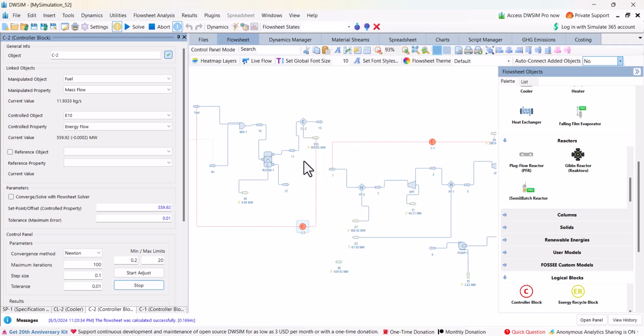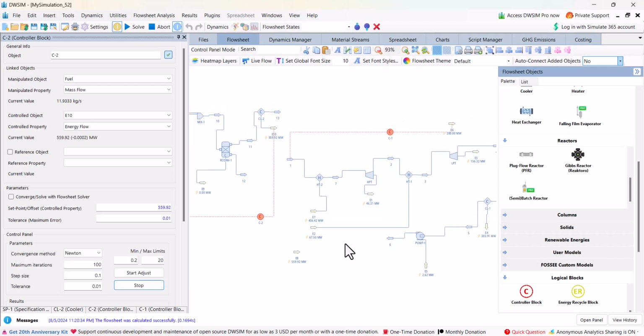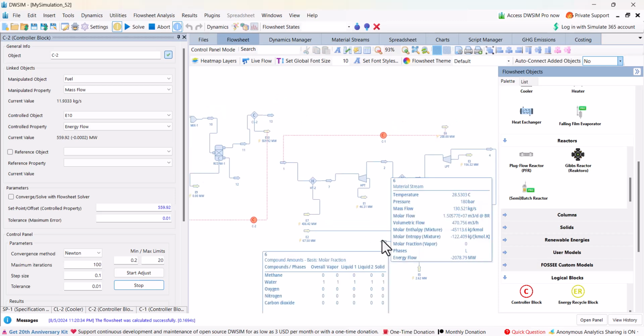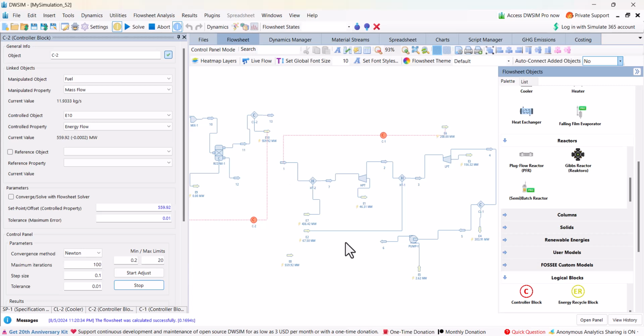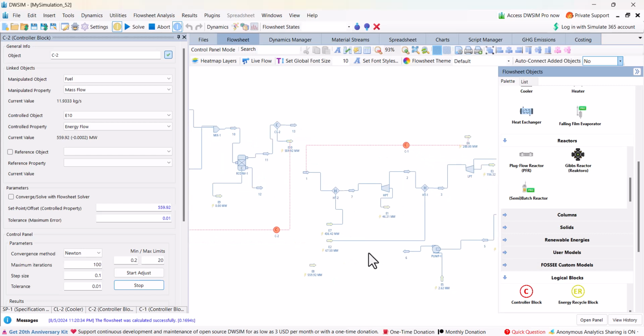Now instead of making it complicated or long, you can just do it by using simple heat exchangers there, and you can use the shell and tube heat exchanger model there, which I'm not doing for this exercise. It is already so long now, like the video is long now, but you can play a little bit around with everything, and you can also add a recycle block with 6 and 1 and recycle it, but I did not do it so that I do not make the convergence difficult. But this is how you just play around with this tool and do your simulations and exercises and assignments.